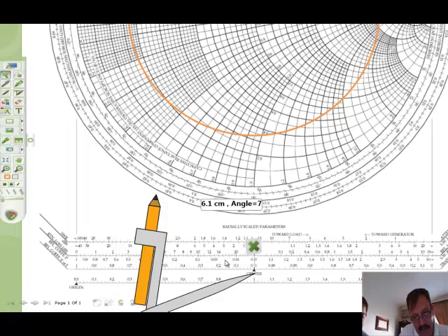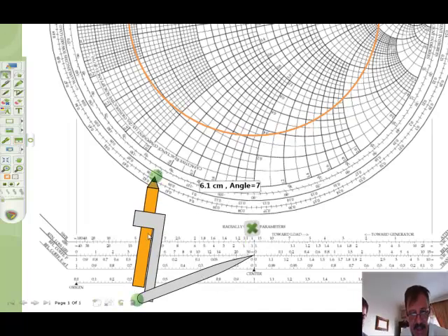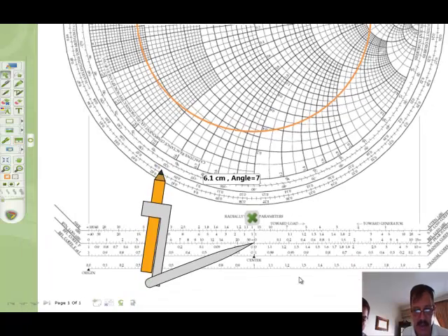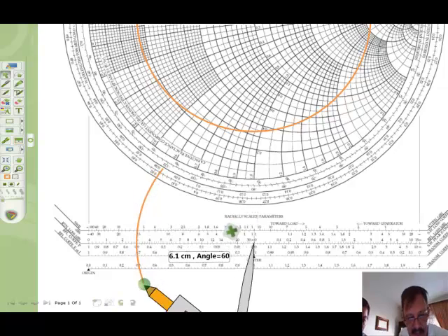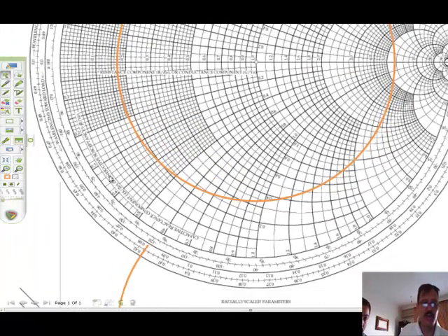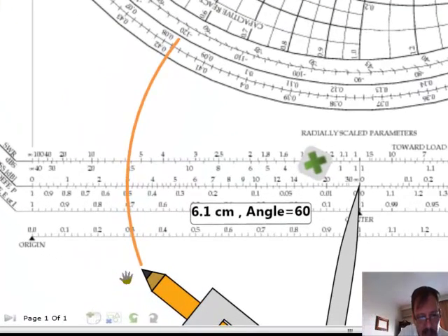There are a number of scales, but we use this one. Now we place the scale at the main point here, and that gives us a reflection coefficient. We zoom to the reflection coefficient, and it's about 0.5.